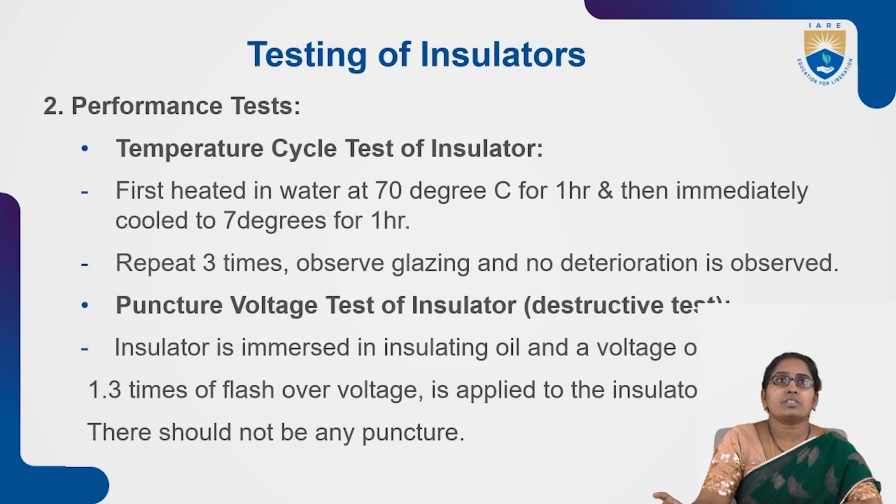So that is how this test is done. They immerse the insulator in insulating oil, and 1.3 times the flashover voltage is applied, and there should not be any puncture. Okay, that is the puncture voltage test.